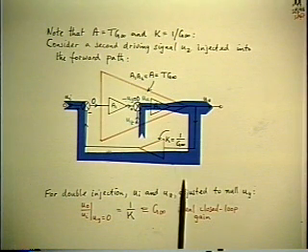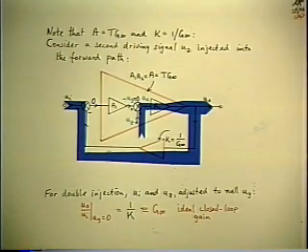Now you see how this last calculation formalizes what you normally do, as we went through at the beginning of discussing the feedback calculation. The difference is that the way you normally do it, you simply assume the error signal is 0. This way, you actually make it 0, and you calculate exactly the G infinity.